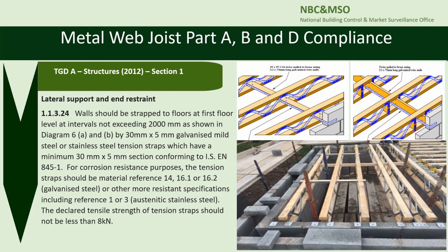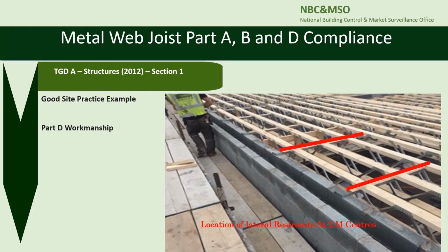Manufacturers of metal web joists have produced manuals which provide lateral support and end restraint details that should be used, and designers need to detail these in the design drawings. This slide shows a good example of lateral restraints provided as shown with the red lines.